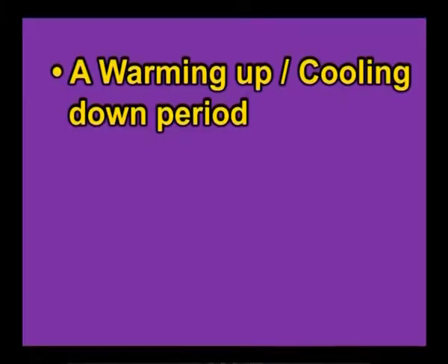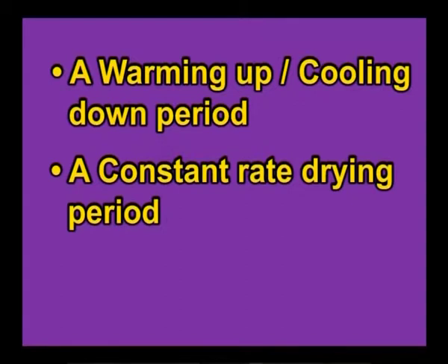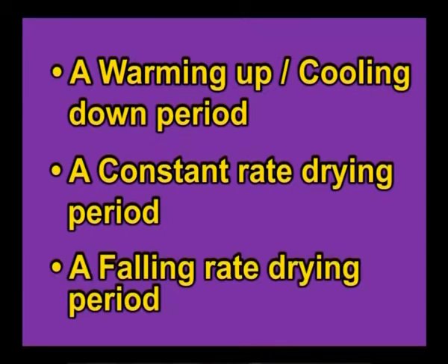There has been much research effort spent on understanding the fundamentals of drying and more complicated mathematical models published in the literature, but a concise introduction of drying still centers on the notion of three drying stages: a warming up or cooling down period, a constant rate drying period, and a falling rate drying period.